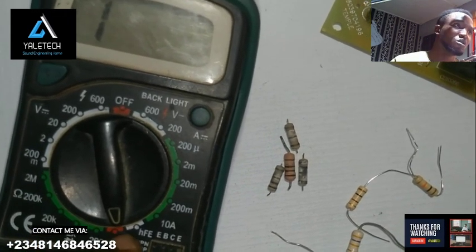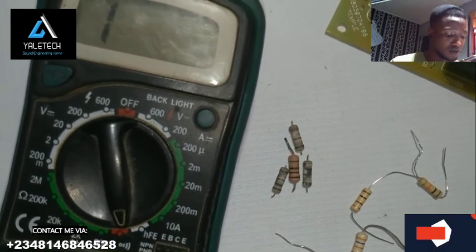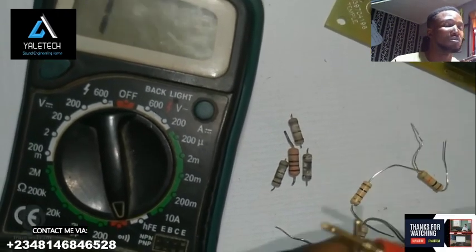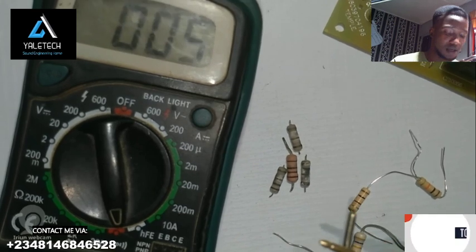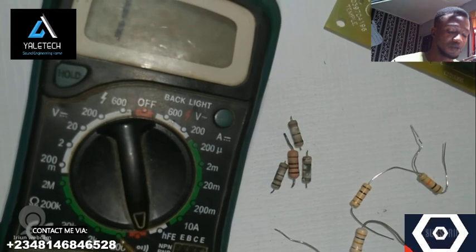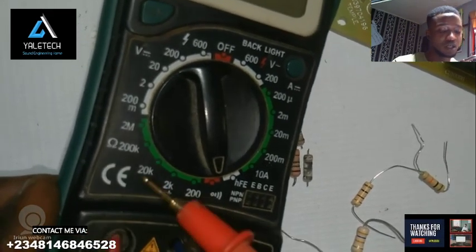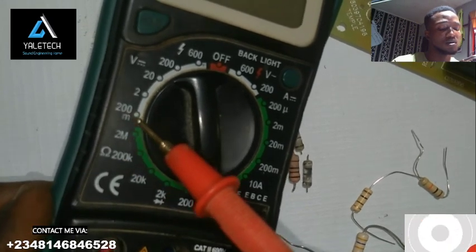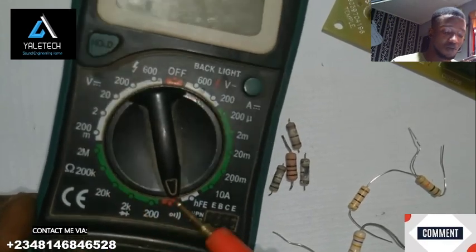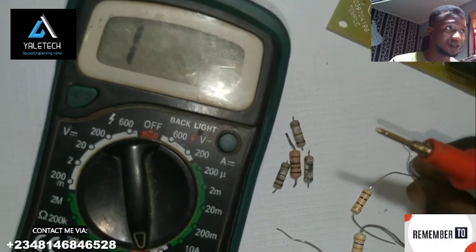Just set your multimeter to continuity. If you don't know how to do it yet, check my playlist, where I have tons of videos that will guide you. Now my multimeter is on continuity, so if I touch the probes together, I should hear a sound. All these other settings measure your ohms: 200 ohms downward, 2000 ohms, 20k, 200k, and 2 million ohms maximum. These are the ranges we'll be using, but first we test with continuity. If it is within range, we at least get a sign that it is good or bad.